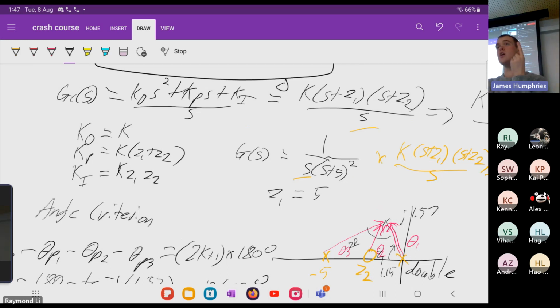I will have my angle criteria and my gain criteria. Gain criteria will always find you K, whilst your angle criteria will find the location of a 0. But here's the thing. Because I have 2 of them, I can put those 2 wherever I want, and they would still allow me to reach the desired poles. Does that make sense?